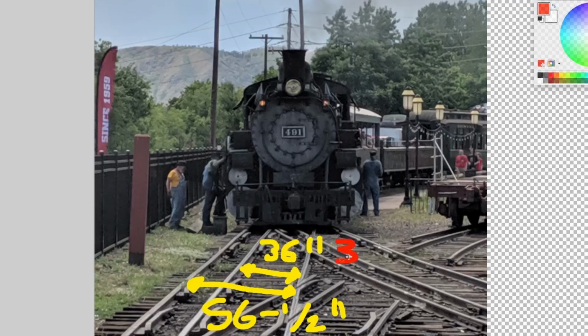Sometimes it's 36.25, sometimes it's 36.5, sometimes maybe it's 36.75. It's getting a little out there. Same thing, standard gauge. Sometimes it's 57, sometimes it's 57.5. But if you're running a fast, high-speed operation, you need to be a lot closer to this. But you're allowed this tolerance because the wheels that the trains have are actually tapered in profile.